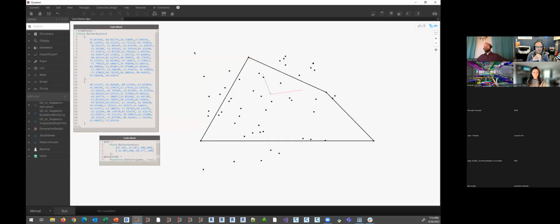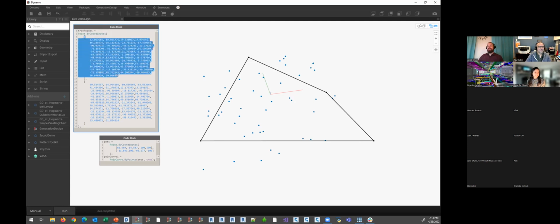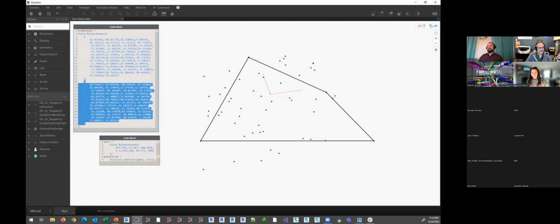I've got a site, right? I've built this site purely in Dynamo using just numbers, right? So what you can see here is I've got, yeah, of course. Why would I use another tool set? I'm the Dynamo guy. So I've got a code block here that is point by coordinates, and then a list of X values and a list of Y values.